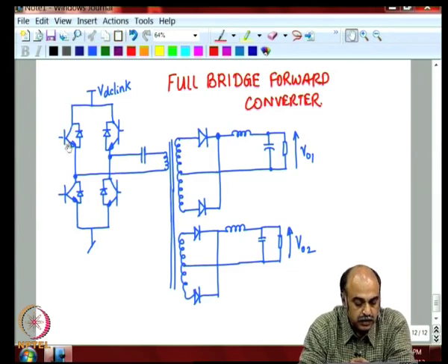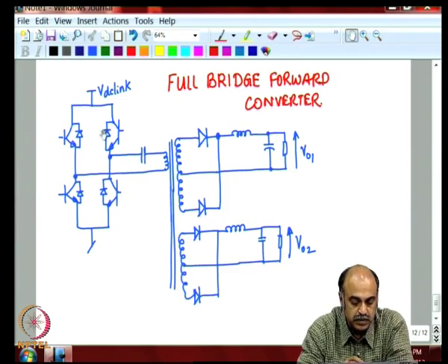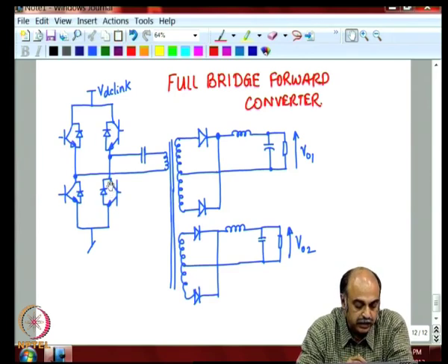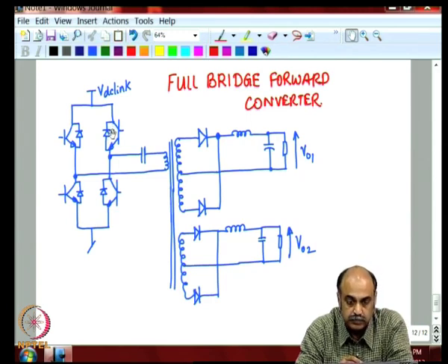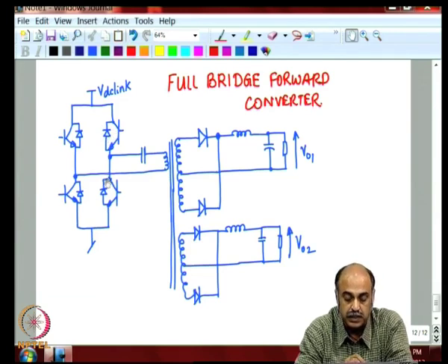In the case of the power semiconductor switches, you need to select them. You are not making them, you are selecting them from the manufacturer's data sheet. So, what are the information that you would need? You need to know the current stress and the voltage stress and the thermal stresses that are occurring in this circuit topology, and appropriately choose a proper device from the manufacturer's data sheet.